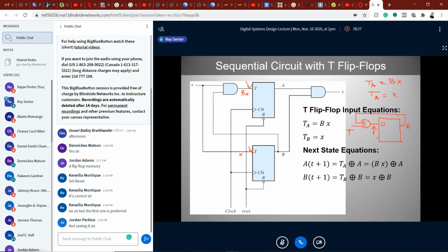So the T value that you get there must go through an exclusive OR calculation between the T and the present state. That is what you see happening there. And therefore, when it gets to the D input, that is when we can use that particular equation, as we did before. Whatever we get at the D input represents the characteristic equation.